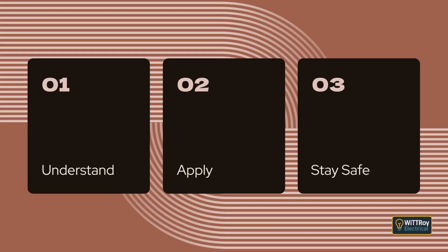These requirements apply to individual domestic homes, the residential areas of other buildings, groups of residential units that share common areas, and external lighting in shared spaces around residential buildings. This clause also states that the RCD must be installed at the switchboard where that final subcircuit begins.